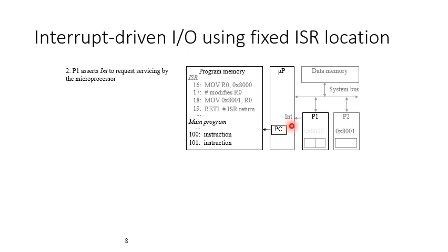So this signal goes high. As you can see here, the interrupt signal is now 1. Interrupt shortcut is INT. And we know that in the next stage, the program counter is going to save the value 100, and then it will move to the interrupt service routine, and it will start from location number 16.